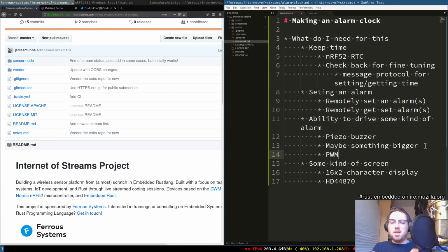And you end up having kind of an analog signal that's driven by a digital signal, because it goes low for a little bit, and then it goes high for a little bit. This is not a good diagram. I should not do diagrams in ASCII. And then it goes low for a little bit, and then high for a little bit. If you have a signal that looks like this, where it's on half the time and off half the time, this is your analogWrite of 50%.